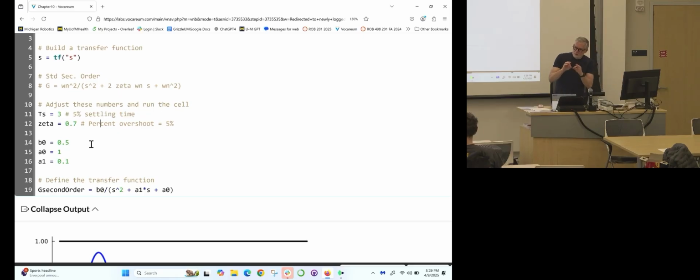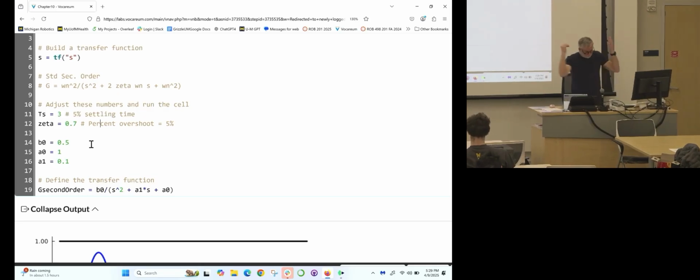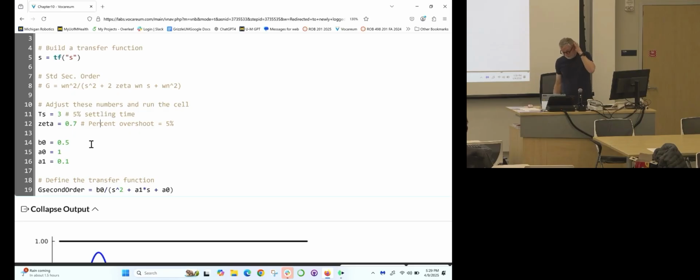Because you may say, oh, I need a damping ratio of this, but if your joint has friction in it already, and that's not in your model, then you don't need to add that extra friction. That's what the damping, the PD is doing. It's adding in the damping part. Okay, so if it's the robot joint. Now, if you already have that friction modeled well, then you can do it more closely. So that's what's going on.